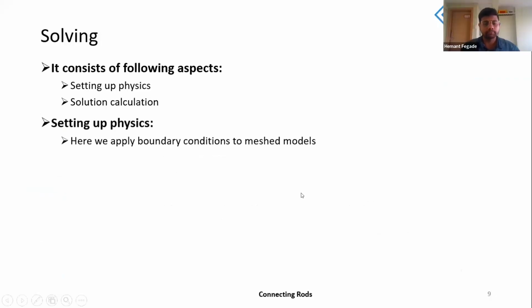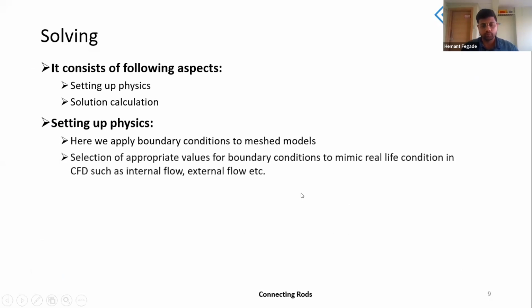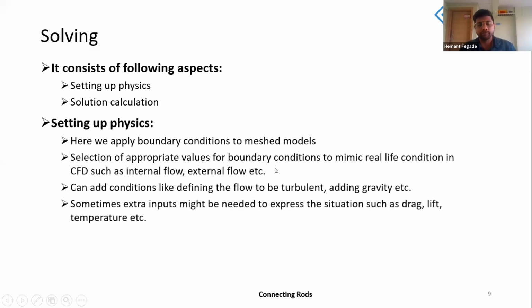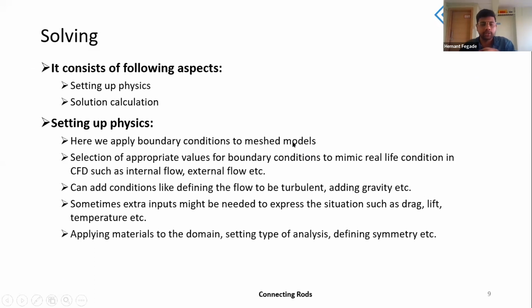So essentially, what we were discussing: when we talk about setting up physics and applying materials, we are setting up the overall case for the simulation. In this case, we will be setting up a temperature simulation, with initial velocity conditions for the air and pressure conditions at the outlet.